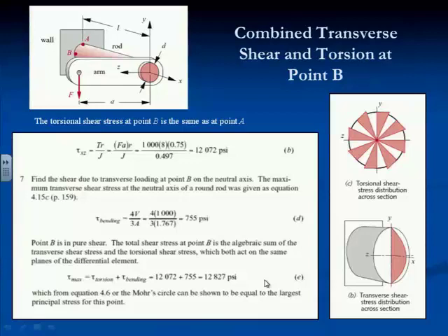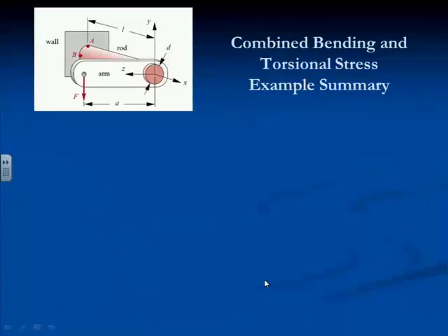And the other issue is, where am I in the cross section? Well, bending, I'm out at the outside. Torque, I'm out at the outside. Shear due to bending or transverse shear, I'm at the midline, at the neutral axis. Anybody have any questions so far on that?